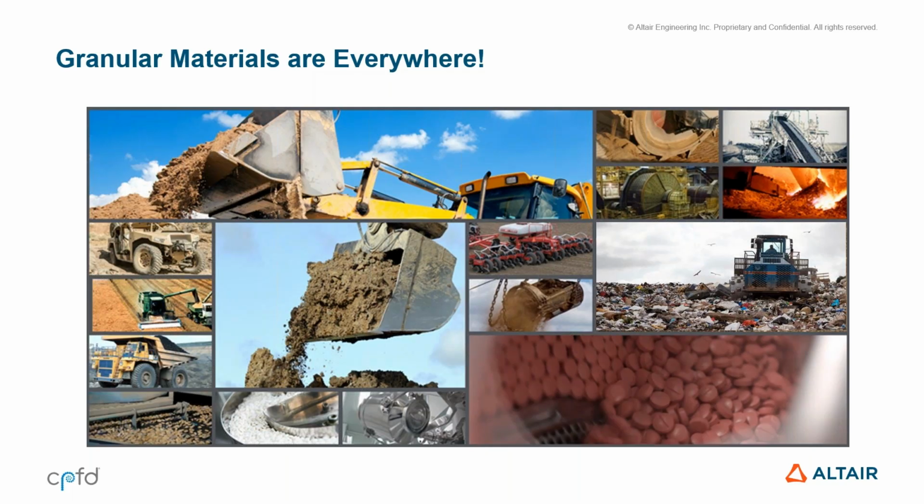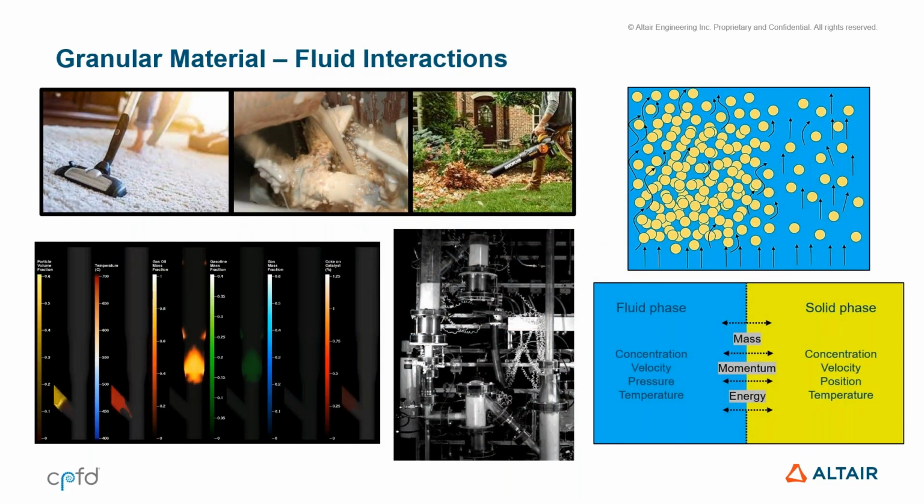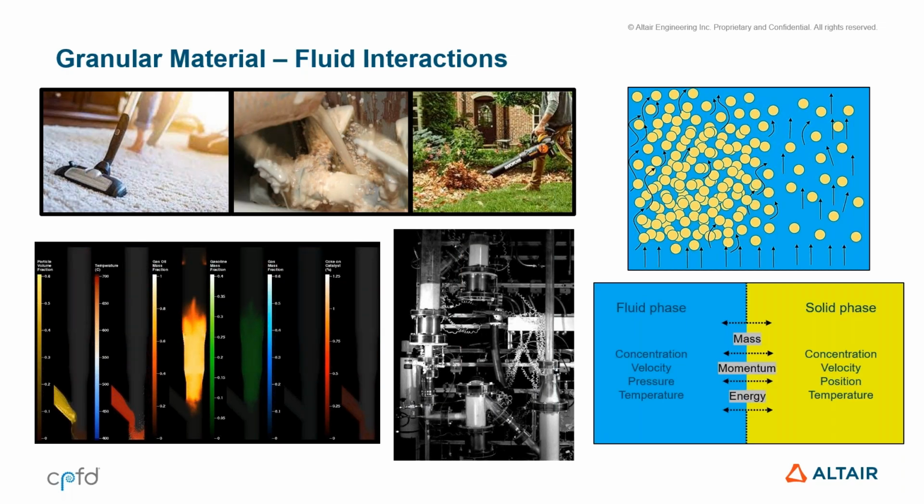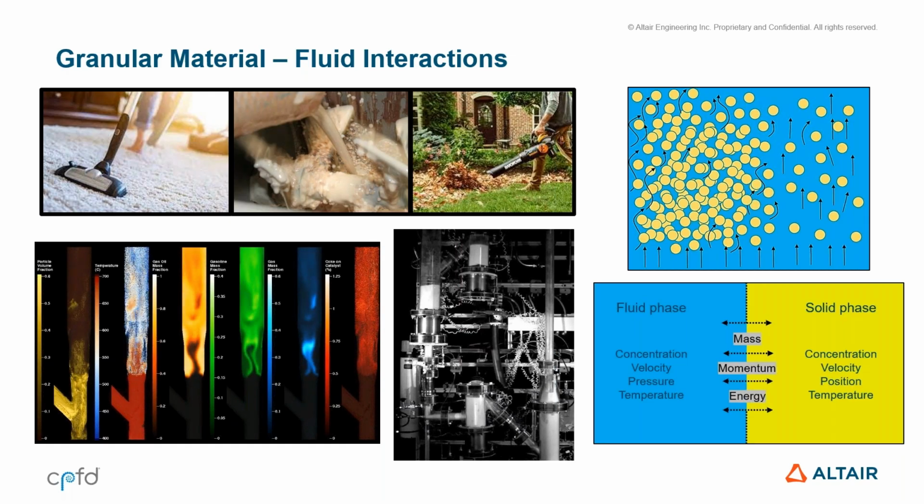And if we take that a step further, in many cases, the granular material does not exist in isolation. Their behavior is significantly influenced by the liquids and gases in which they are found, and this further ramps up the design challenges that engineers face. The type of particle fluid behavior can vary greatly, either from dense phase to more dilute flows. There can be heat transfer, chemical reactions, or you can be talking about an application that's at a small scale, such as in the case of a vacuum cleaner, right up to the largest of chemical reactors. These particle fluid or multi-phase flows are encountered across industries, including the energy sector, agricultural applications, mining, oil and gas, chemicals, and pharmaceuticals.